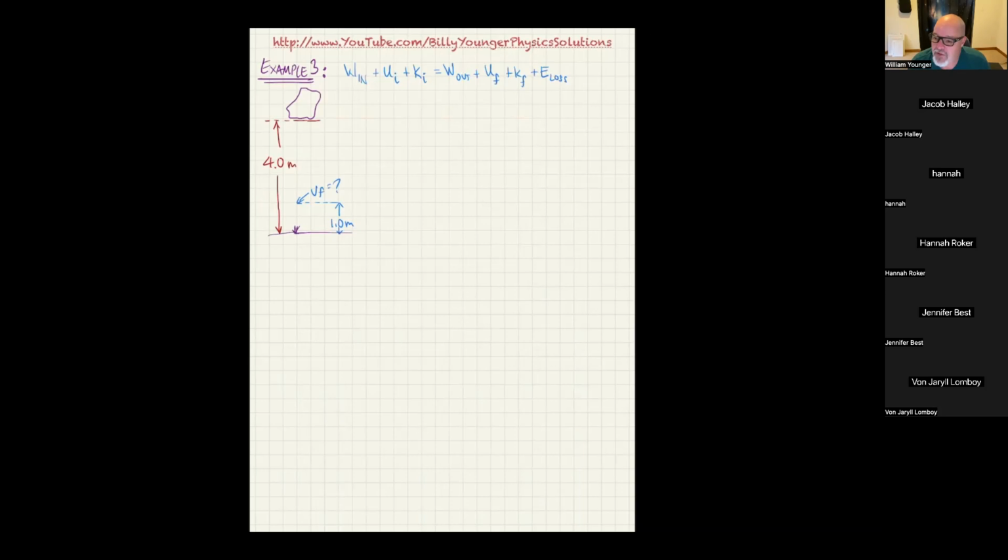Every type of source of energy that you're putting in should have, in some sense, a work in term for it. The main thing you want to do is make sure you count all the sources of energy put in and that you count them and use them exactly once, and that they all turn out to be positive and on the left-hand side. So if energy is going into the system, you want a term for each way that's happening, and you want it to be positive.